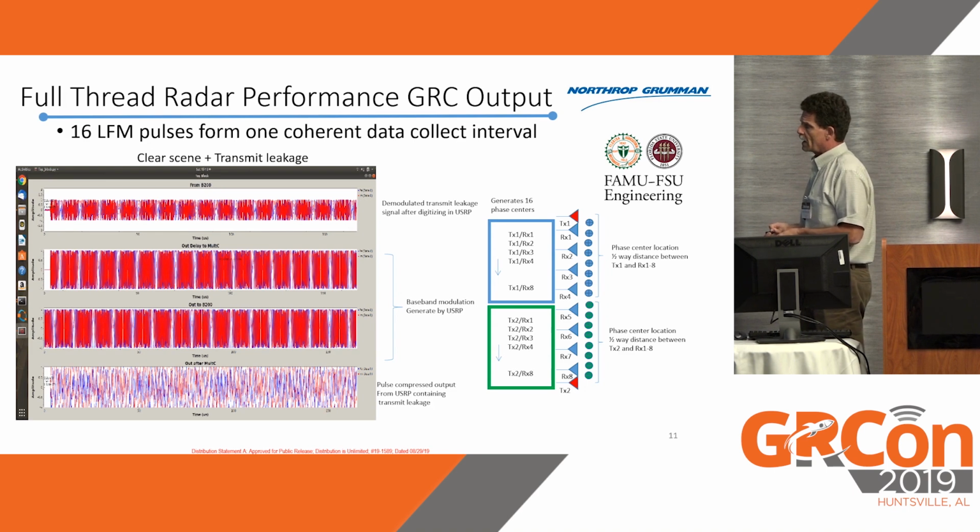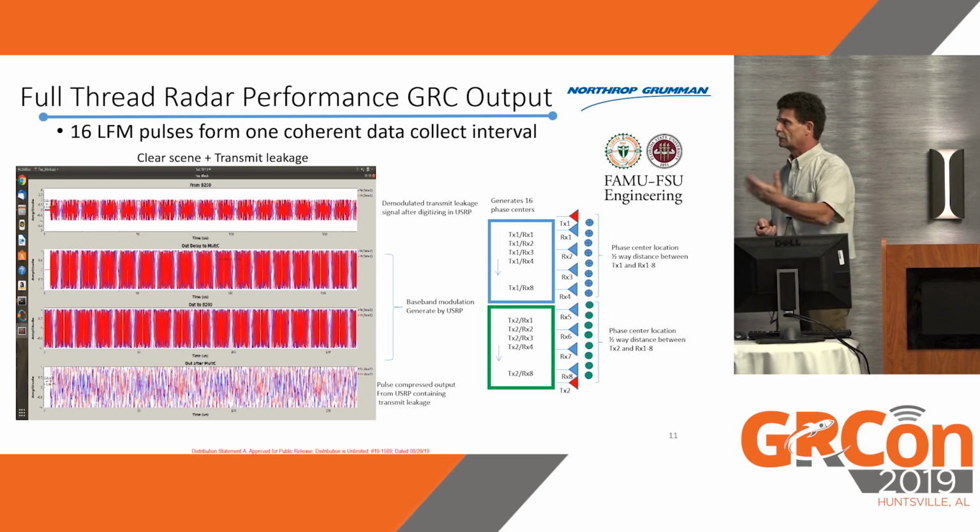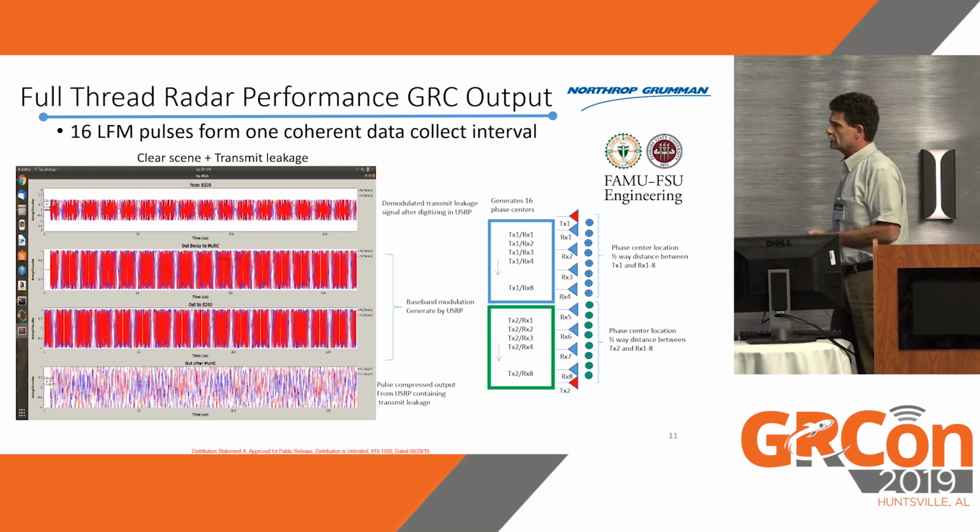The signals that go out from the radio, the baseband modulation generator, that USRP, you can see these are the LFMs. There's 16 LFM pulses that go out. So there's one packet of samples that produces all this as a binary file that the USRP takes and spits out. And we coordinate the switching for each one of these pulses to coordinate with the right transmit-receive pair.